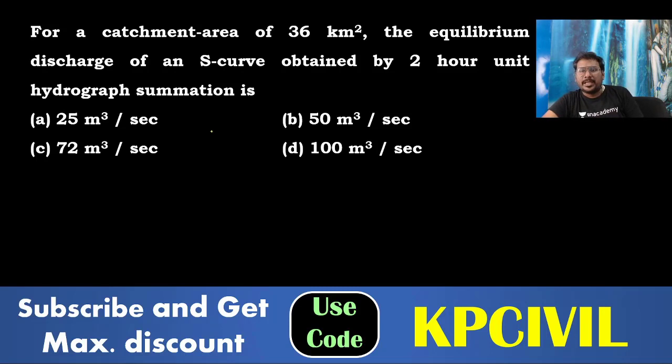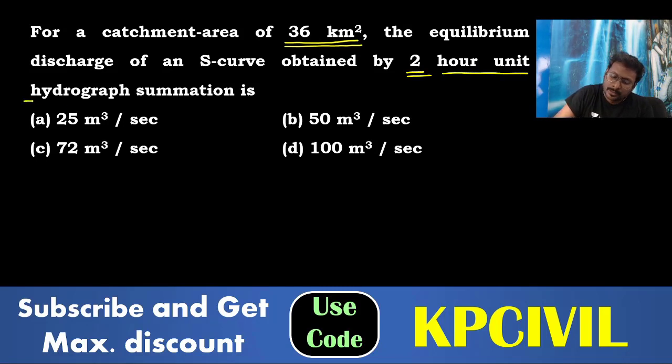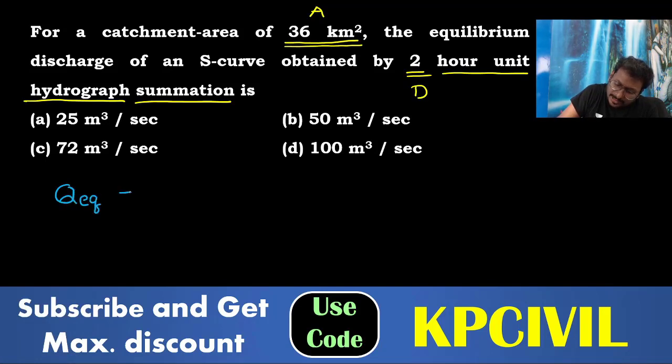For a catchment area of 36 km square, the equilibrium discharge of an S curve obtained by 2-hour unit hydrograph summation: A is 36 km square, D is 2 hours. Just now we discussed the formula for equilibrium discharge of S curve. Tell me, QEQ.